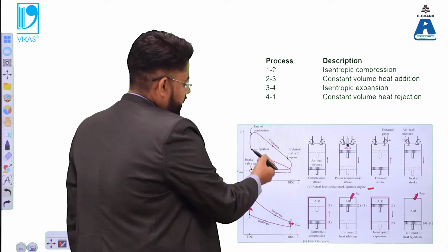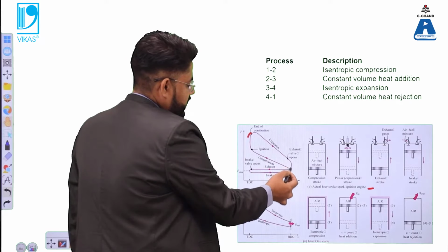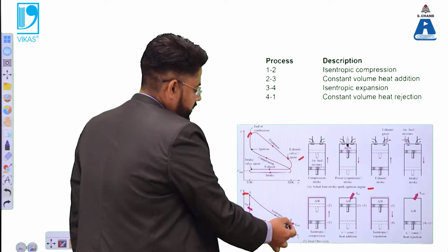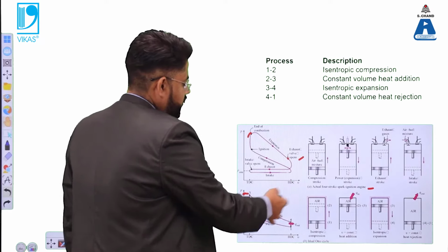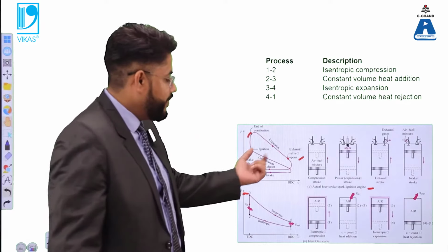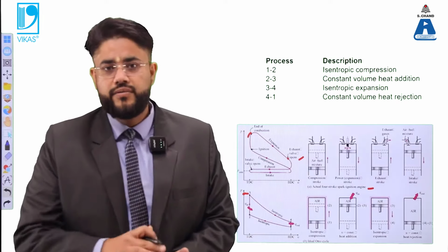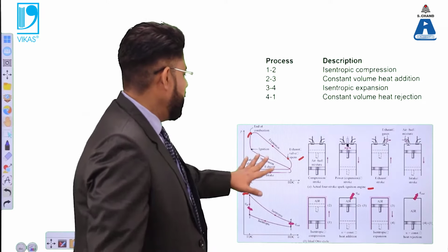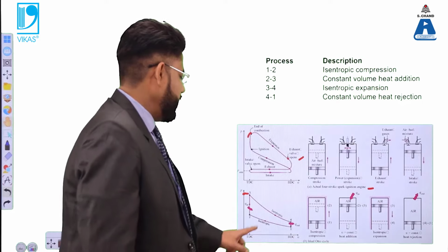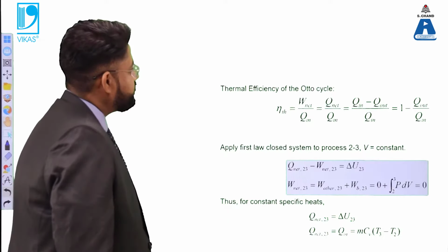And then it has compression, and the pressure value reduces, then the expansion, and then when the valve opens, it has a different value as shown in this particular figure. So this particular diagram, although the shape is the same, the pressure and the temperature conditions are no doubt reduced to a certain extent. So this is particularly related to the actual 4-stroke spark ignition engine, and this is the ideal Otto cycle case.